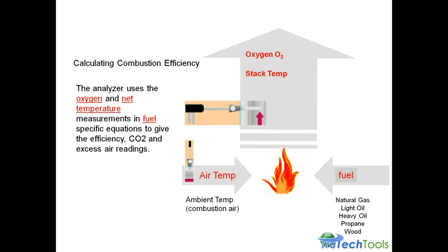it goes off a predefined heat content for that gas. So it's looking at, okay, well, how much heat did that gas develop? How much heat's going up the stack? How much oxygen's going up the stack? And it's giving us a reading on the analyzer. So, in a nutshell, that's all it's doing. And it's got a second sensor in there that's your carbon monoxide sensor that we're using to determine safety.